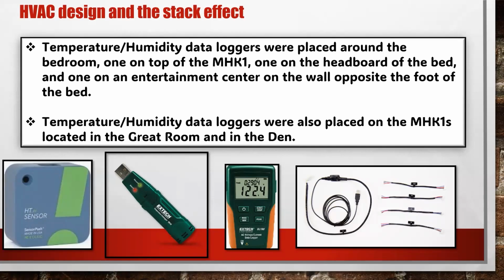I'm sorry, I was going to say a lot of times we don't have the option to undersize. That's a suggestion for the suggestion box to Mitsubishi: smaller systems. Maybe we're driven just by the need for the number of heads. I need to have this many heads in the house, and it leads to oversizing because the house can't really support that many heads for the size, the amount of heat they're going to put out. It might be better to do one ducted system if that's possible.